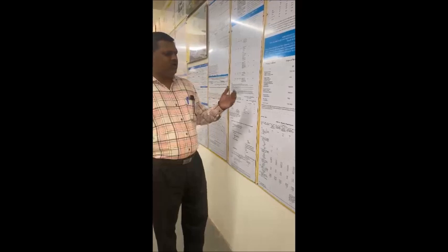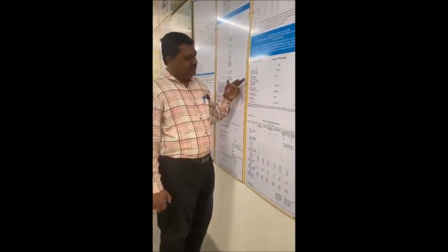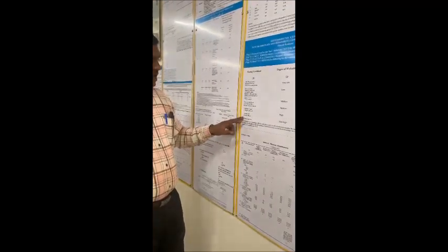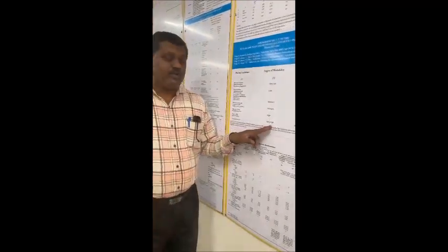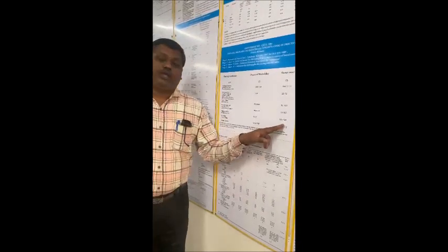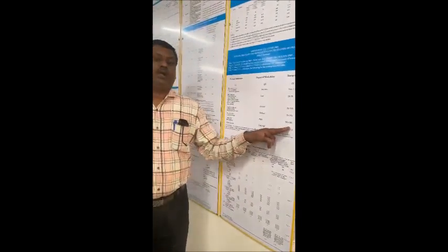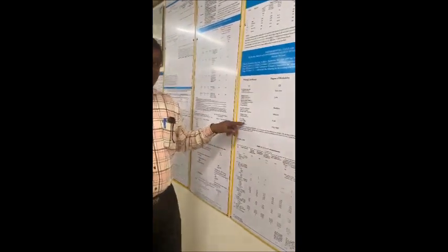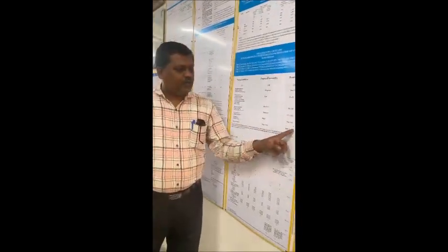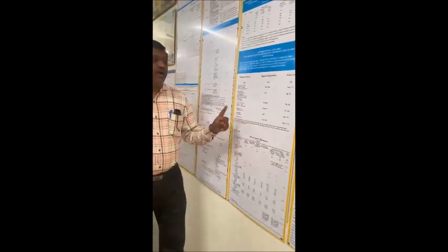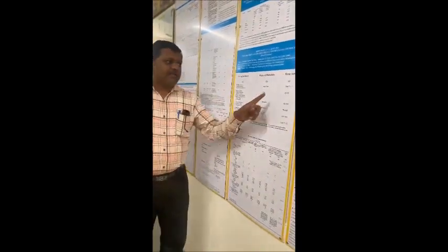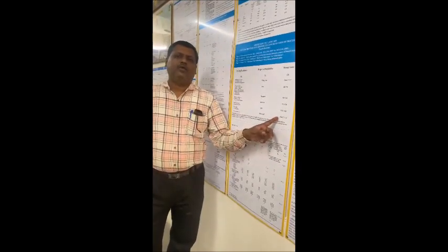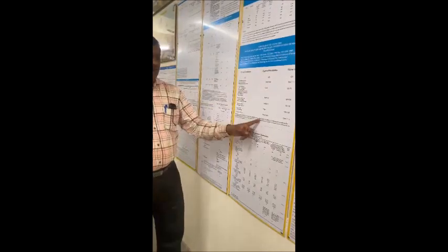You can pause the video and then continue. This 180 slump concrete is most suited for this type of work, which we can call trenching concrete. Degree of workability is very high, and the slump is more than 150. It is about a pumpable type of concrete, where the concrete will be placed through a tremie. Okay, so the slump values play an important role, and for a particular placing condition the slump values are important. Slump values indicate the cohesiveness and homogeneity of the concrete, and this is the degree of workability.